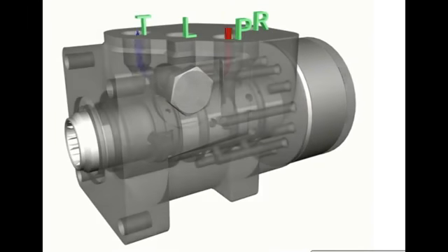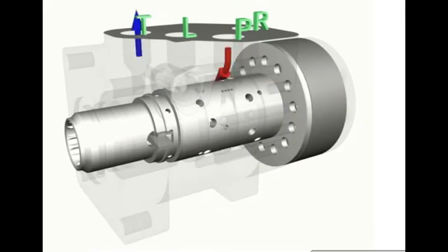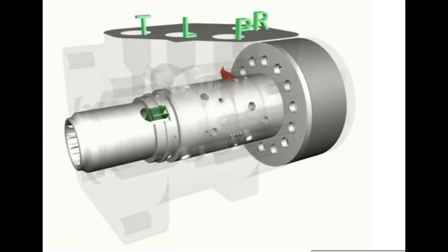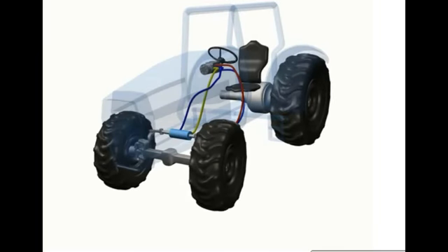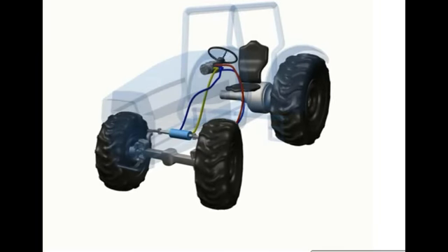Without rotation of the steering wheel, the centering spring holds position of the spool and sleeve, and the fluid flow is allowed to pass through the pressure port to the spool and sleeve and to the tank port of the steering unit. Rotation of the steering wheel counterclockwise rotates the spool in the sleeve against the force of the centering spring, allowing fluid to pass through the rotating spool sleeve valve.